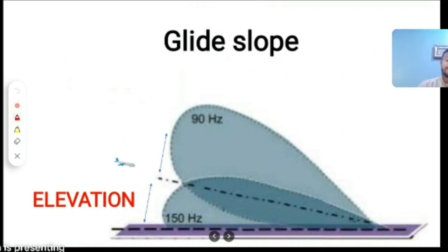Okay, now coming for landing, Mr. Raza. You are coming for landing. So now, actually in ILS you only tune the localizer frequency. The glide slope automatically captures, right?